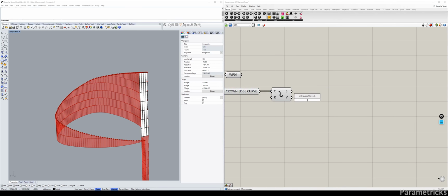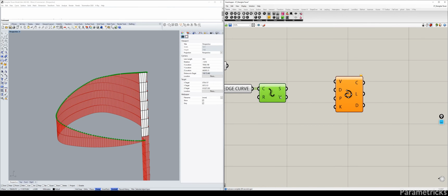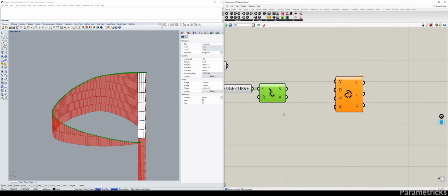So I'm just going to quickly do an interpolate, not that, an interpolate curve. That is weird. Where is my? There we go. We have to watch out for one thing. Since we exploded this, we have multiple segments where each segment has a vertex to it. So we have double vertices, so we need to clear those first.